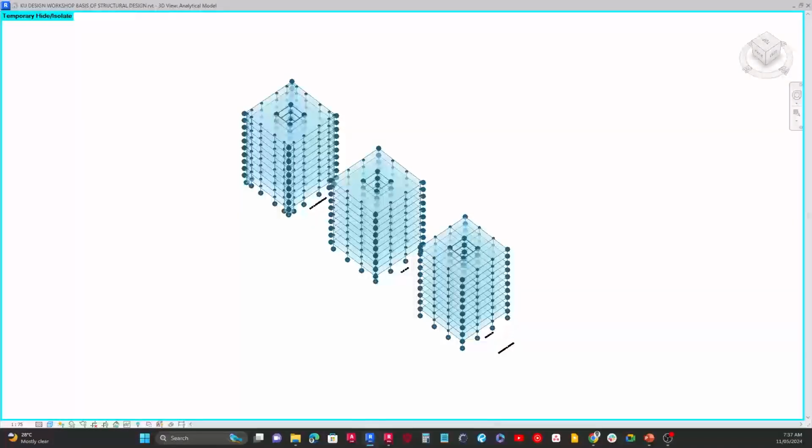Basically, I won't say that they are different. So for instance, when we see C30, that means the cylinder strength is 30 megapascals. That's the cylinder strength for the concrete. But when we see M20, that means that is the mix strength. So M is always going to be referring to what is actually done on site.